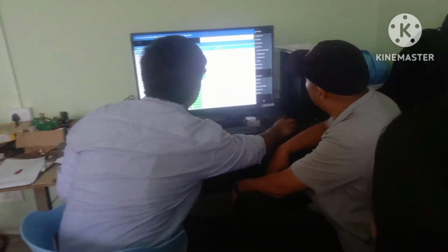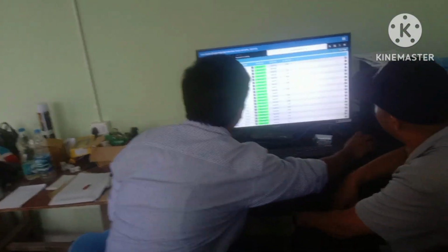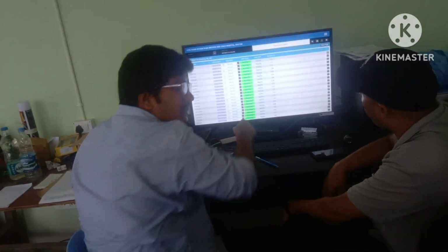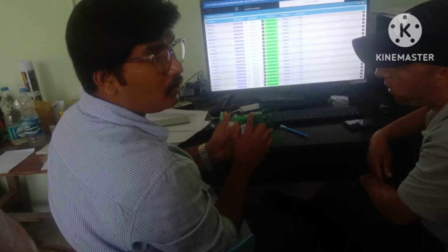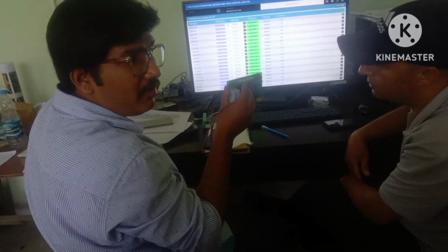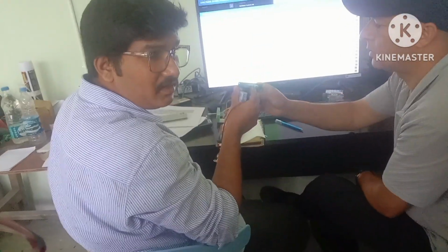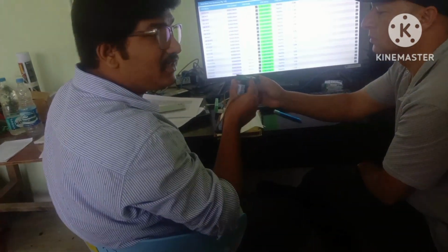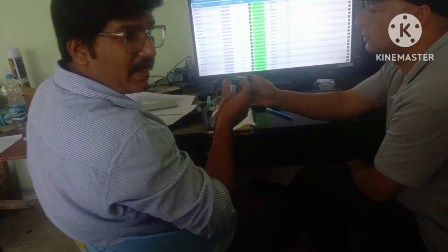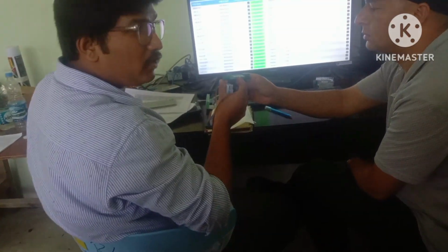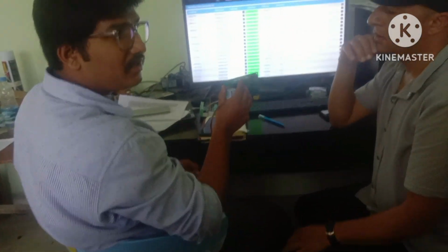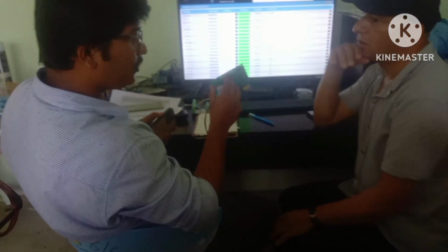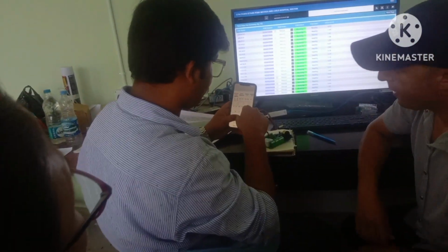We are on the fan screen only. You can see the status here, and the status is coming from here. Yesterday we observed that we had given the command but still were not getting feedback, and when we physically visited, it was on. So that means there may be a loose connection here, at the 11 and 12 terminals.